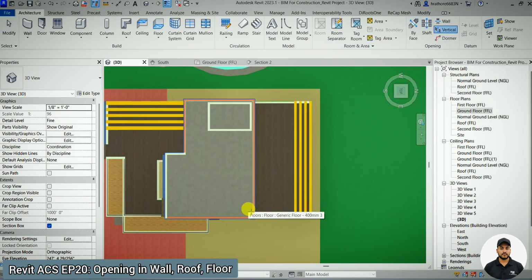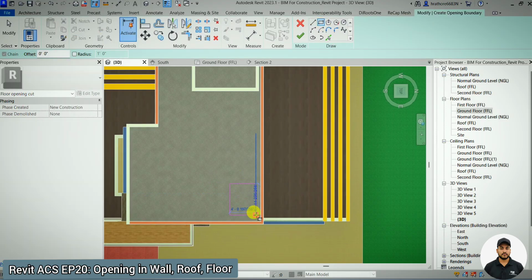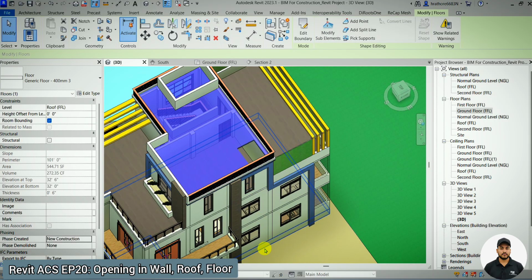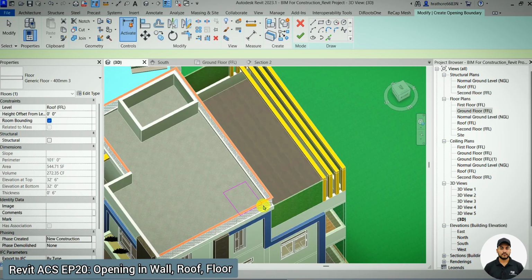So if you choose either of those features, and you have selected a floor, and you create an opening here, let's say this one, the opening is created in this particular floor only. It is not going down through all levels. So this is not our riser opening. In case of a riser, we need the full riser shaft penetrating through all the floors, and it will be counted as a riser. In case of a lift, as you can see, the lift goes from the ground floor up to whatever the building's top level is. So we need a full separate riser for the lift area. So how can you create this one?